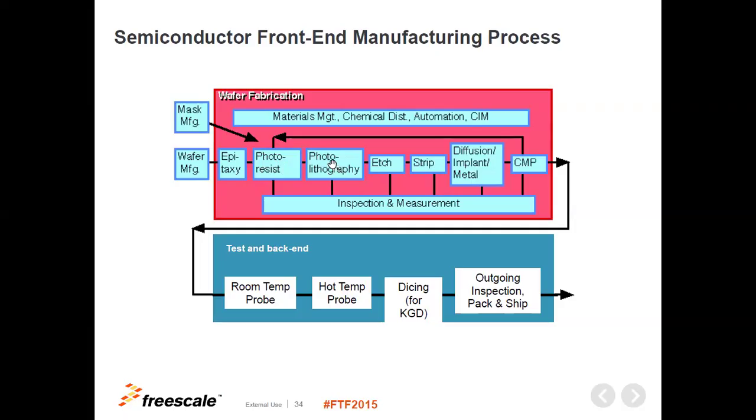When you see, for example, in the motherboards, that there are areas that are more, you can say, copper-covered and so on, these areas are properly realized by this system of photoresist first, and then I take out the resist that I don't need to create a channel by the photolithography process and so on.